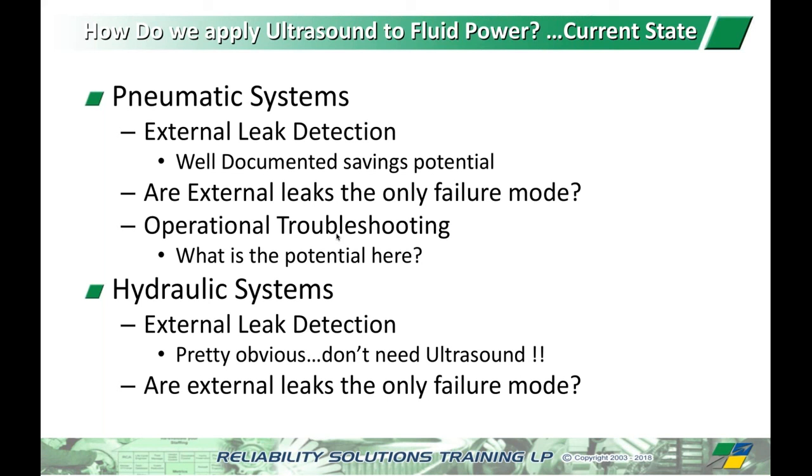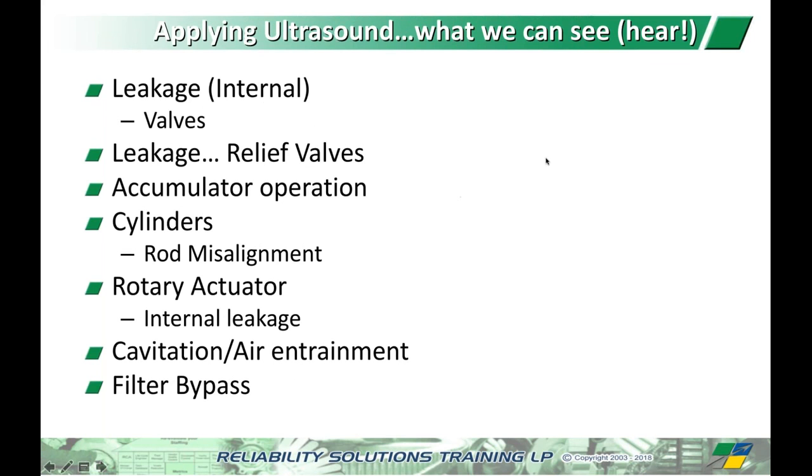A lot of times it's more of a comparative type thing, knowing what a good one sounds like and knowing what the bad one sounds like, rather than necessarily something that's quantifiable. Oh, I've got, with the external leaks, so many dBs means so many CFM. We're not kind of doing that. And with bearings, your 8 dB rise means you got to lubricate it. It's not necessarily quantifiable, but certainly being able to identify when that leakage is there, it can bring a lot to the table.